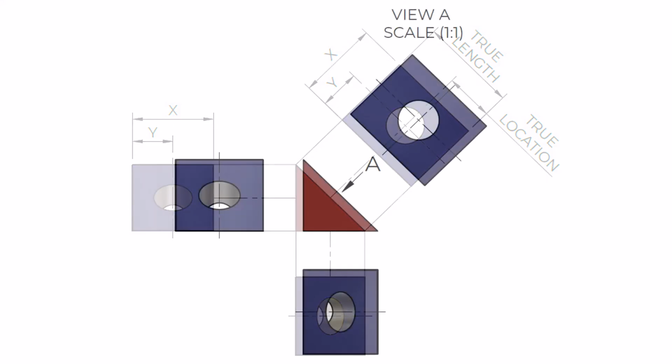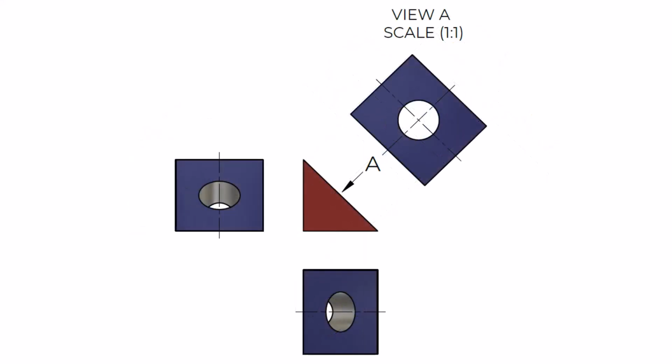Instead, the direction line will be introduced to show the direction of the view and the identification with a capital letter. Usually, on the drawing before the capital letter, I would add the remark view. When you have a large number of sections and detailed views, I believe that it is easier and faster for a manufacturer to read the drawing.